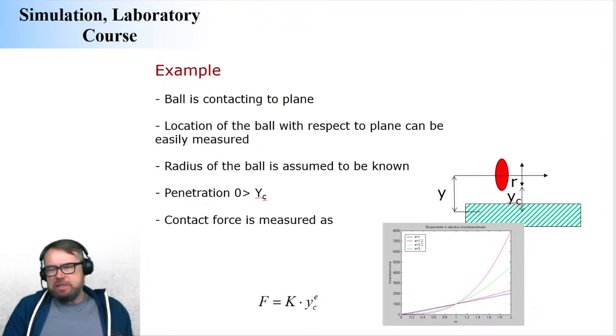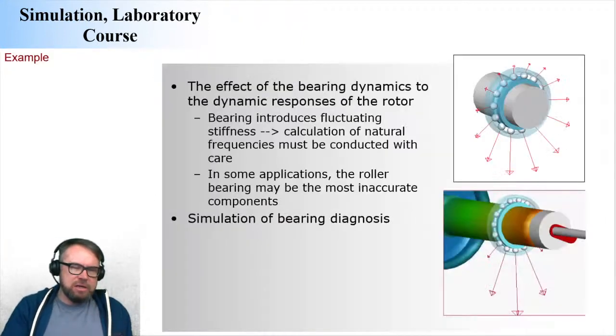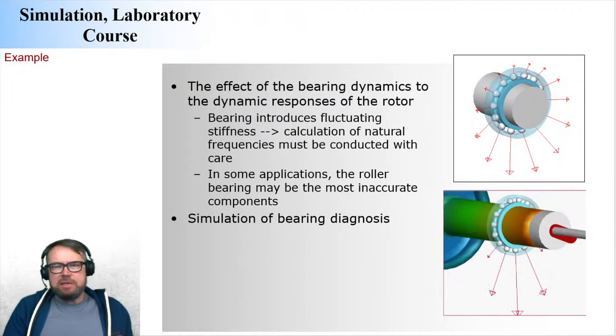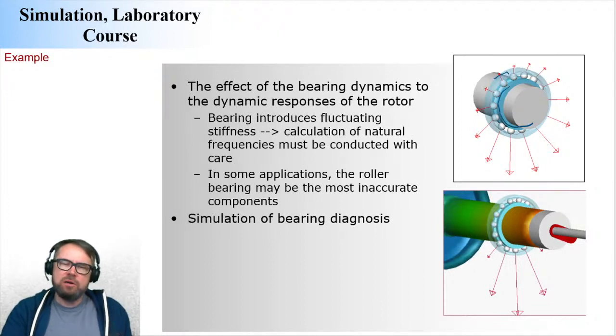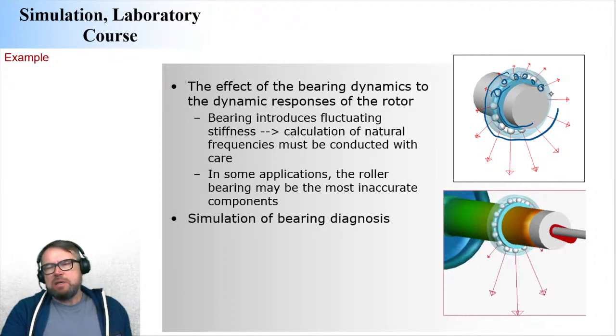So I'm going to skip this example here, but I'm going to show you another example. This is something that is bearing modeling, where the ball bearing is modeled by using this kind of penalty forces. Basically, there's an inner ring here, an outer ring, and then the balls. And the balls are not really the balls, but a geometrical representation, which is not the real representation.